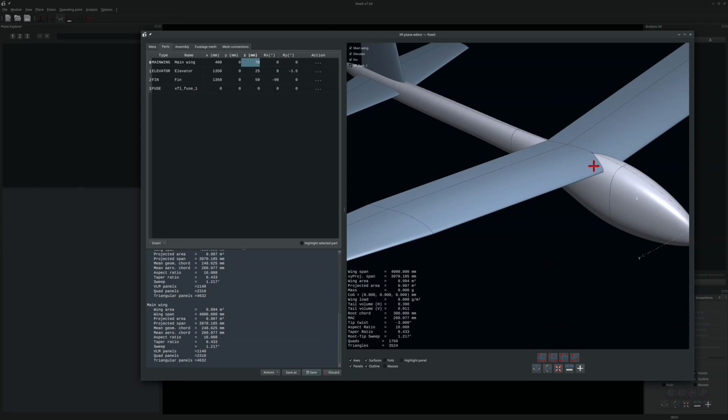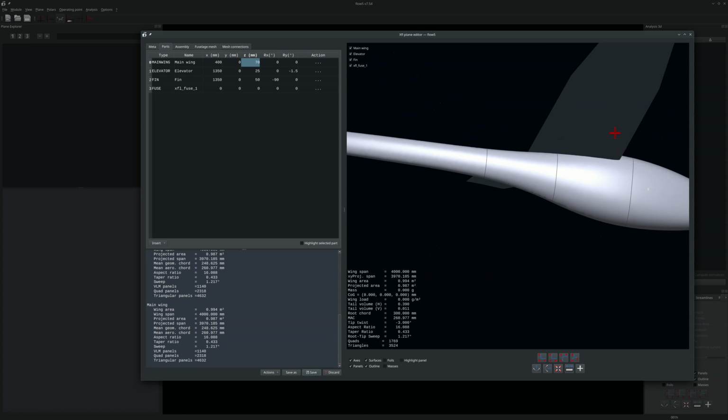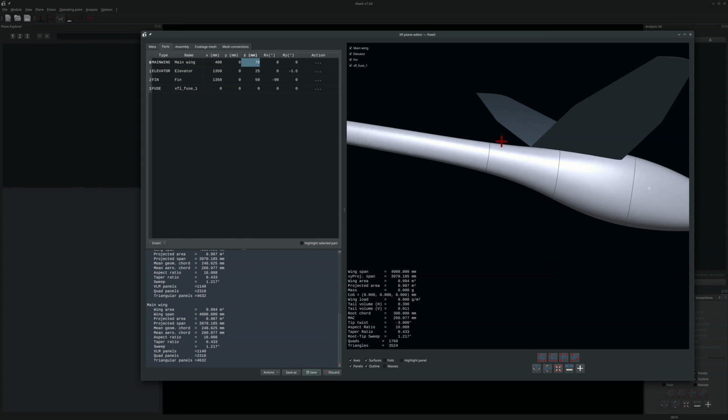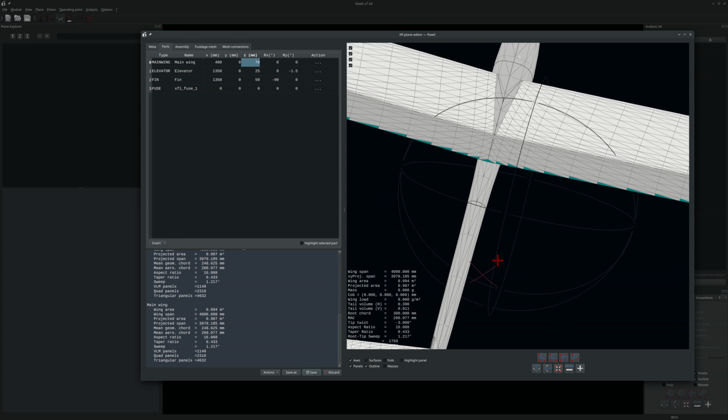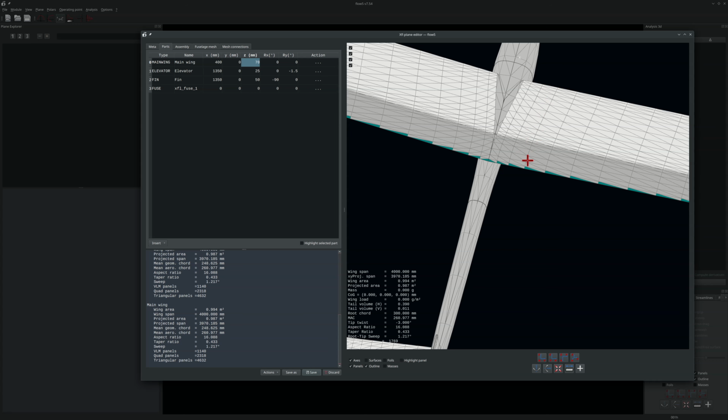If this is the real configuration of your plane, well, do something about it. Either increase the height of the fuselage so that it intersects cleanly the wing, or move the wing downwards, still escaping the elevator panels. But try to avoid this configuration. One reason being that it will create warped strips in the chordwise direction, and flow5 calculates along strips which it expects to be more or less aligned in the X direction.